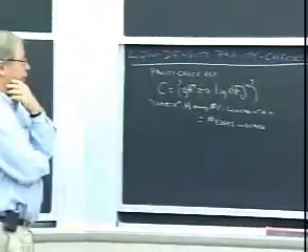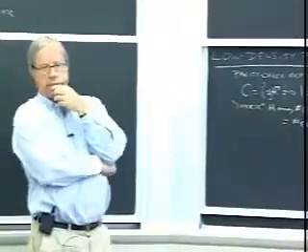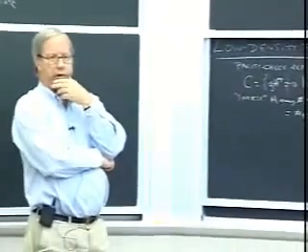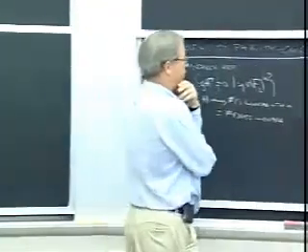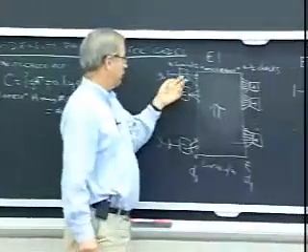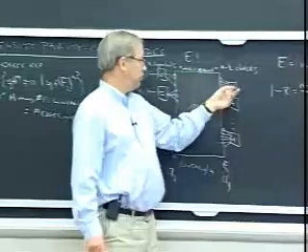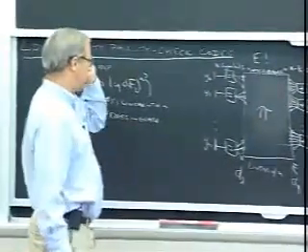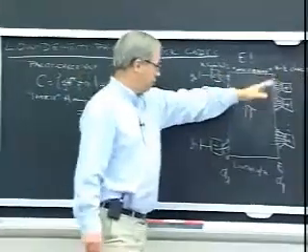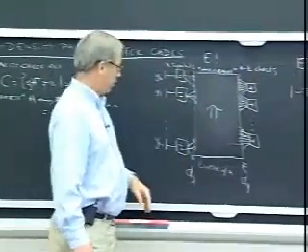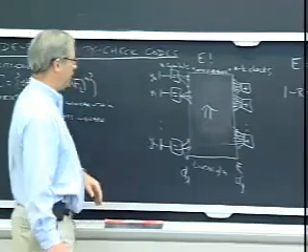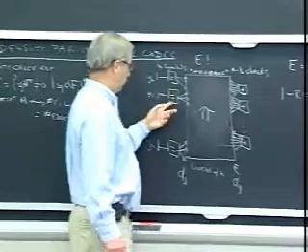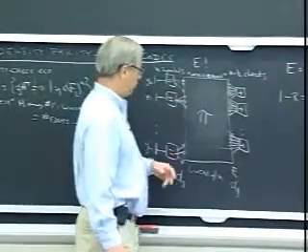And now how do we decode it? Well, we use the sum product algorithm. We've got a code on a graph. In fact, it's a very simple graph. Notice its characteristic. It's, again, just got equality nodes and zero-sum nodes, or check nodes. These are really the simplest codes. We can more generally have more elaborate codes here. That's one of the things Tanner did in his 1981 paper. But this is very simple. All of our internal variables are binary.